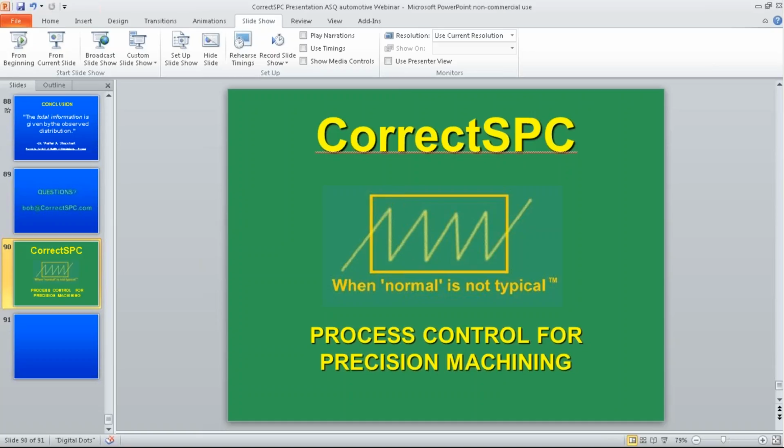And I'm not really sure. I've dealt with some laser machining, and laser machining, you know, it has its own specific issues. That's why I tried to focus this on cutting methodologies, because I know for sure the tool wear applies to that. But in fact, this type of charting methodology probably has other uses that I haven't personally been able to verify, such as plating. When you have plating chemistry distribution, you start out with a lot of chemicals in your plating bath, and then they drag out over a period of time, and then you need to make an add, and so on and so forth. You end up with this type of a variation also. But I just personally haven't applied it to that. I could use it as an example, just as a potential for people that may be in that to take a look at.